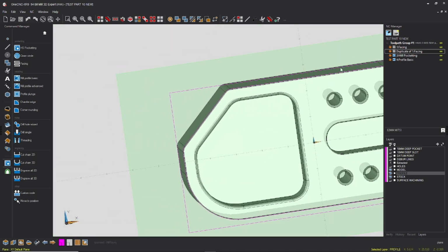So if you zoom out and look at what that looks like, there's your 5 degree line, 10mm long, comes in, goes all the way around, and comes off at a gradual angle. That way you don't get that dwell line that you see when you comp on and off of parts. It just phases in nicely, and it's starting off the job, which is another thing to point out, which you get with a lot of CAD CAM.